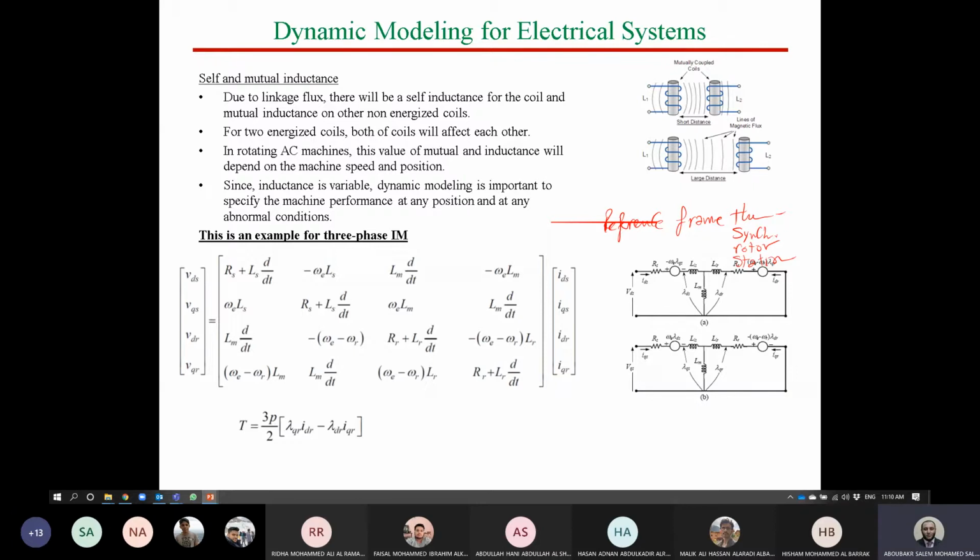For that, if you make the same for machines, for an induction motor, for instance, we have the parameters of the stator, which are a function of the frequency F1. All of these parameters are a function of frequency F1 on the stationary reference frame. However, if you stay on the synchronous reference frame, which means you are going to rotate with the synchronous speed, you will see all of these variables as constant. Is it clear, guys?